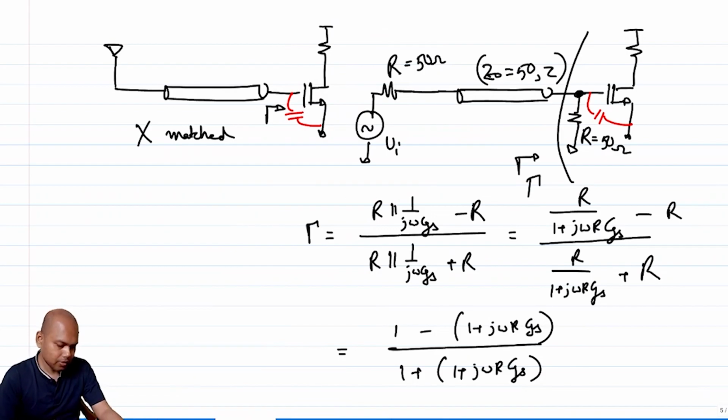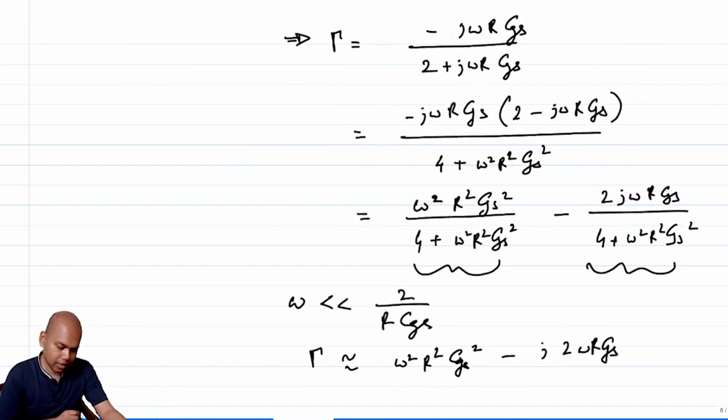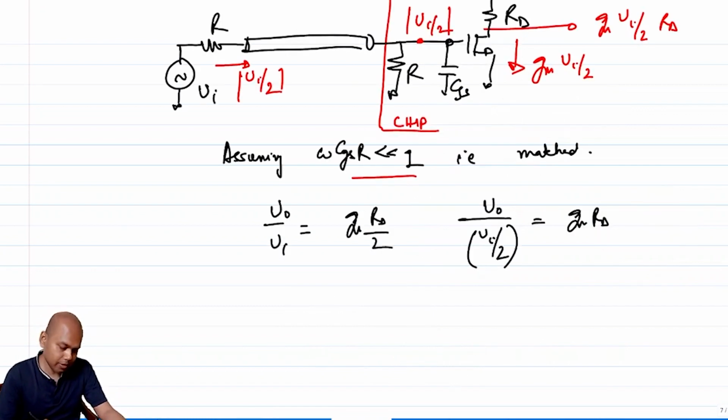Then, once we understand the efficacy of matching, from the receiver perspective, we tried to figure out ways of using single transistor circuits to implement a match. We saw an example with a common source amplifier, how we can match. The common source amplifier intrinsically has a capacitive impedance, so that cannot be used for matching, which means we need to put an explicit resistor R. Under certain conditions of frequency, it will give you a decent match.